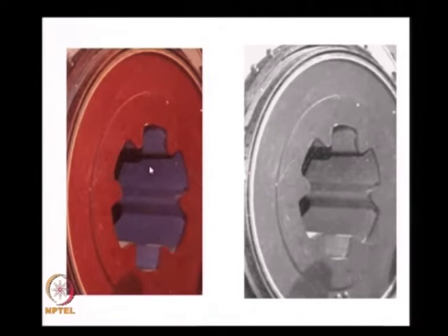The burning surface area, this is the inner surface of the grain, this is the length of the grain in this direction. The surface area would keep on evolving like this, and like this, until it touches the outer surface of the grain. The minimum thickness from this to the case is what is known as the web thickness or the thickness of the grain. Mind you, there are several thicknesses. It could be from the vertex or tip to this, or it could be from this to this.